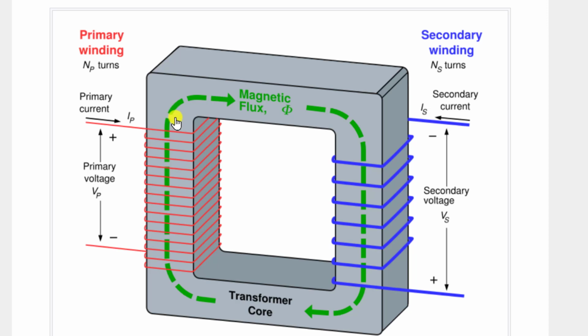So the magnetic field here will be north pole up and then north pole down. It'll flip-flop up and down. The magnetic field in the iron is going to be flip-flopping every time this electricity flows back and forth again. That magnetic field would reach through the iron to this other coil. So now you have a magnetic field that's flip-flopping inside of this blue coil. But now, since there are fewer loops on here, it will push and pull less strongly. So over here you would have lower voltage.